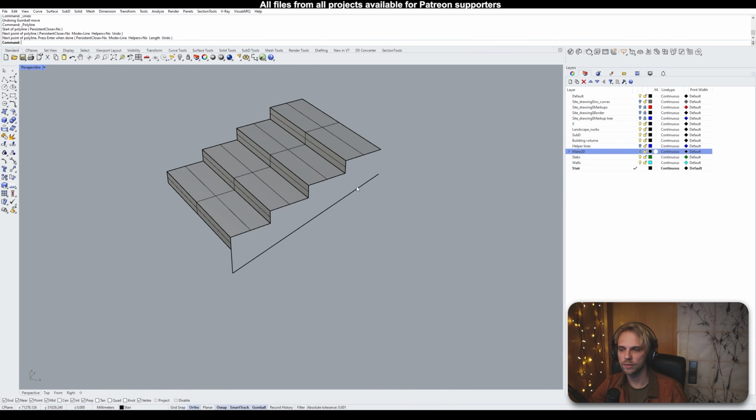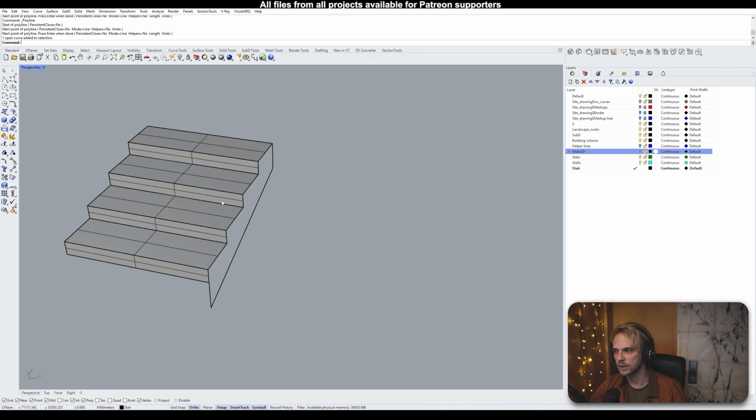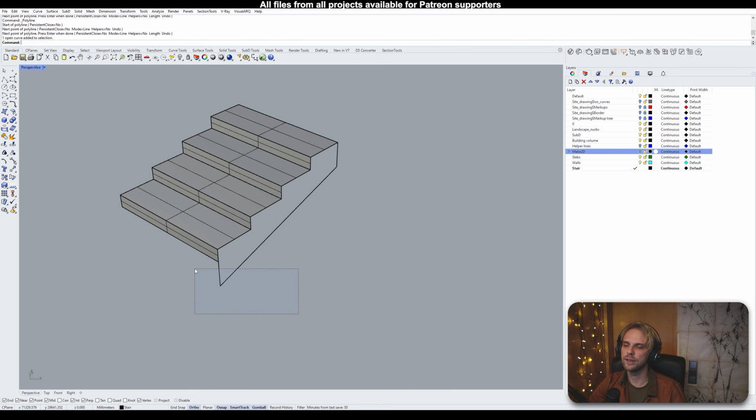Finishing it off like so, we end up having this boundary, which we can fill in. So we have the sides, and then you fill in this little end that's going to be Boolean differenced out by the floor slab either way later down the line, and you eventually end up getting a staircase.